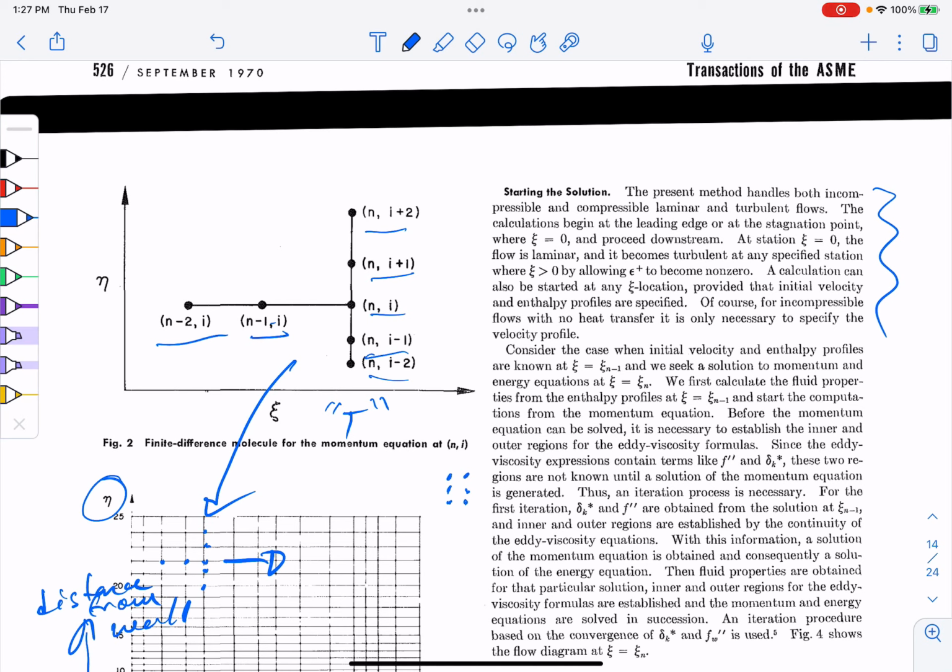I guess the good thing is you're letting it slowly ramp up with some kind of function that you assume, which is another empirical turbulence model for transition. The bad thing is you're not letting the equations do it. It's always better to let the equations let things naturally evolve. So I don't know if there's an easy answer to the question I pose, but it's a pretty insightful idea.